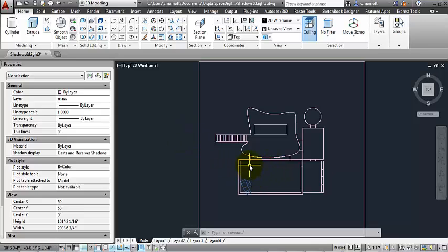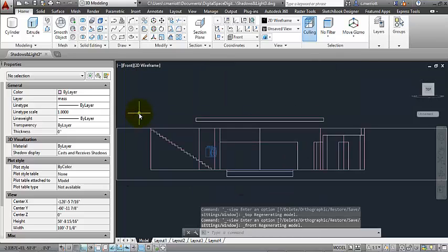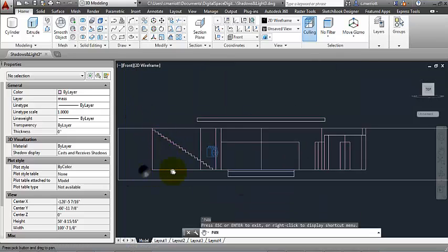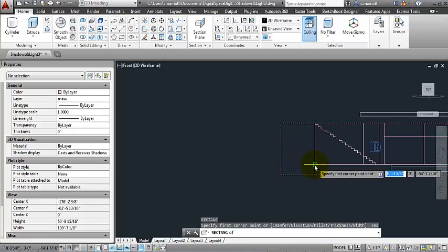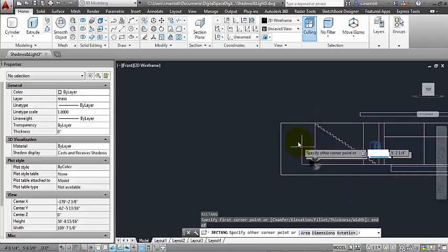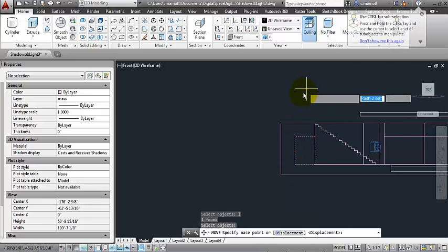Also, as you think about how you're going to construct this, you want to know the height as well. So this opening here is 8 feet high. So my screen is going to be 6 feet by 8 feet. Now I'm going to go to the front view, so I'll be in the orientation that I would be when I insert this screen. And I'm going to make a simple rectangle. I'll just snap to a point here. That rectangle is going to be 6 feet wide by 8 feet, and then I'm going to move it over